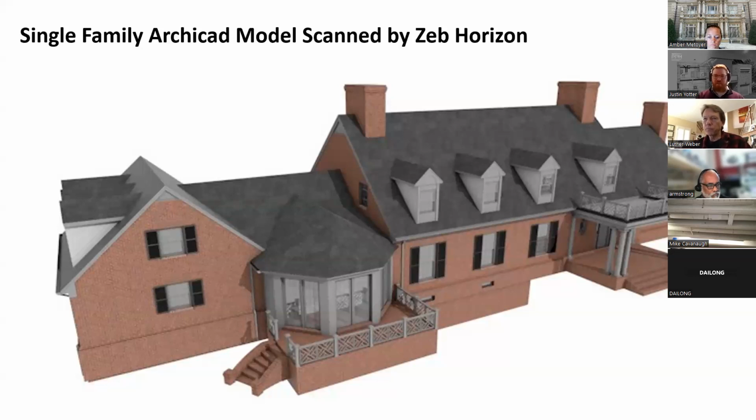And here's an example of a project we scanned using the Horizon mobile scanner. It's a 9,000 square foot single family residential house located in DC. It's a beautiful property that was built in 1836. And as you can imagine, there are no as-builts to reference prior to us doing as-builts on this property. So the client requested our remodeling package, which includes floor plans, roof plans, exterior elevations, and still photos. This project was modeled in AutoCAD, and it took about 36 hours to completely draft it from the point cloud data. The total time spent on site to survey the property was roughly 6 hours.